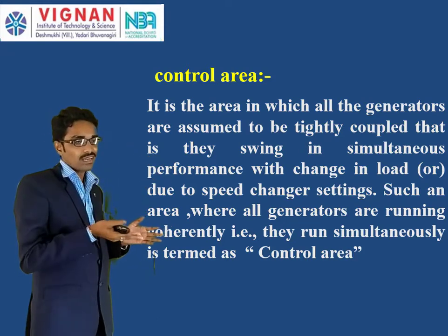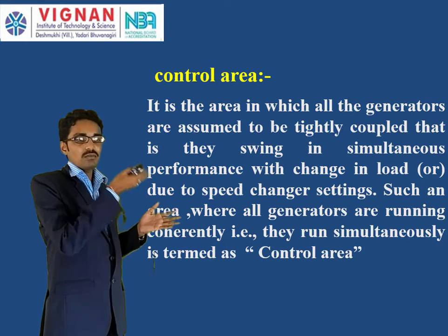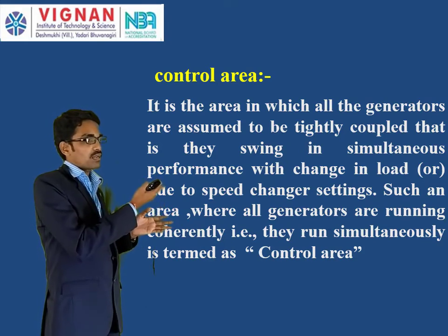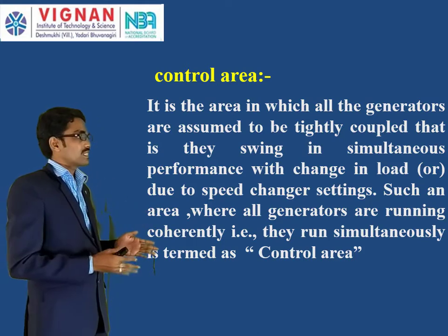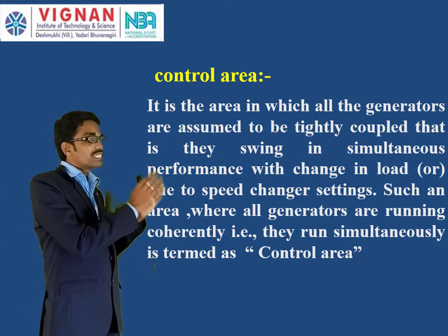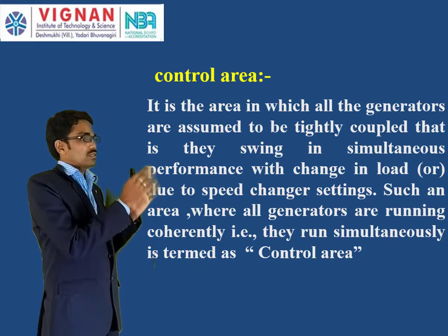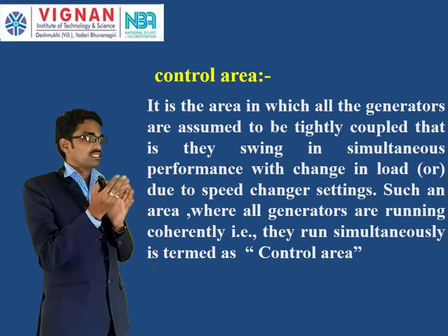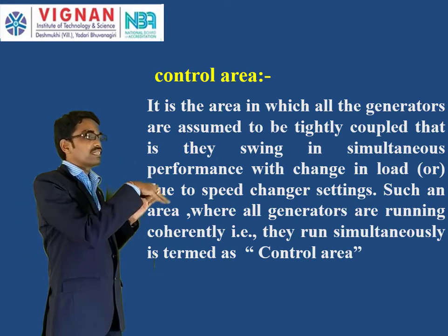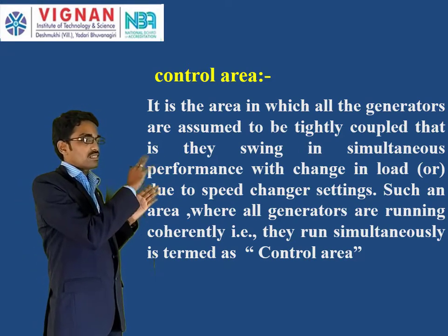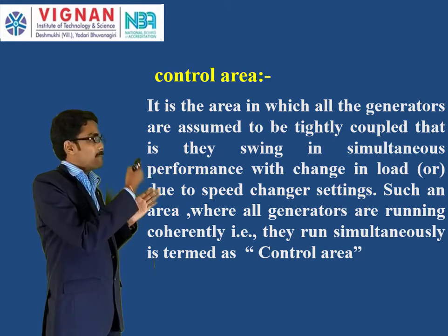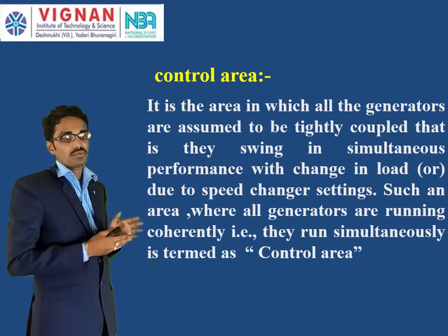That is what we call the steam valve. The steam valve changes according to the amount of load to be met. If I consider some area, whatever generators are present in that area, and there is any load change in that area, then what happens? The generators present in that area change their setting by changing the steam valve input.